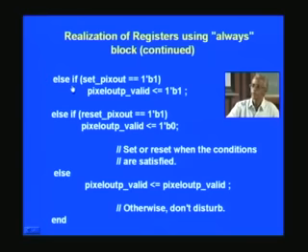So, one more else if set pixel out, which was a bar b c bar, if it is 1, we need to set this pixel out p as 1, and if reset is asserted, then we need to reset it here, and that is what we have put in the comments. And if none of these are satisfied, then you just use only one else, because this indicates that it is the last in that category of else if. And in this case again preserve the same value. That is, do not disturb the contents.